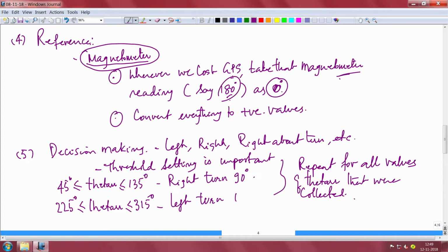So somehow your magnetometer is keeping track of the direction essentially. So when you say reference, your magnetometer is now calibrated with respect to the GPS and the particular direction in which you are proceeding. You are starting by saying everything is 0 now, and from here I will start tracking the magnetometer accordingly. That is what you are saying in step number 4.